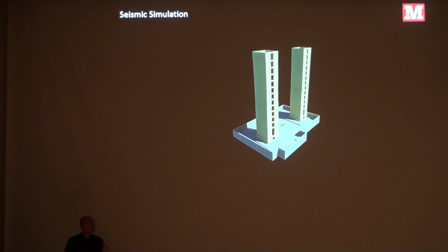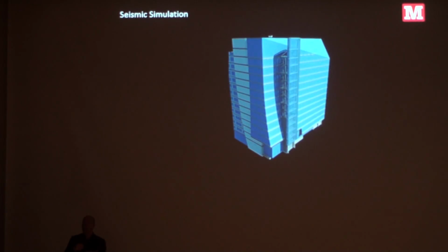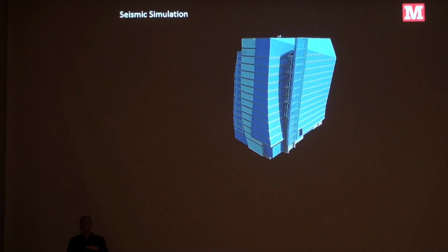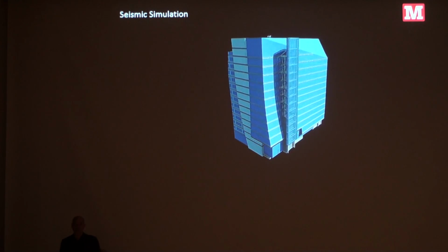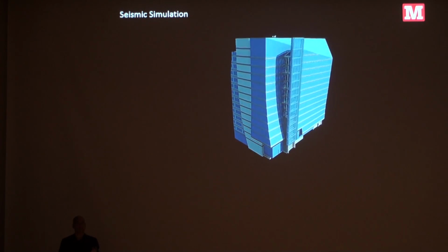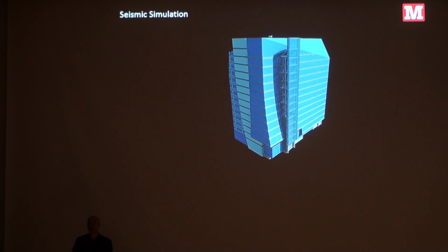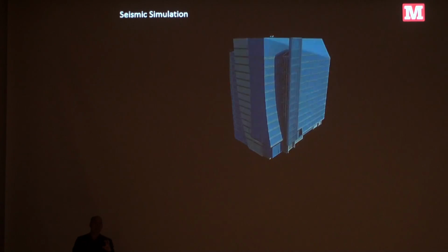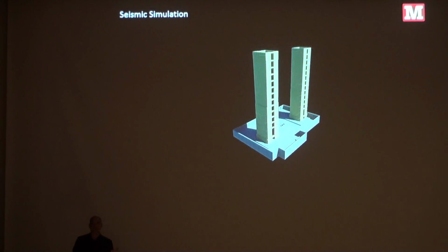The next thing we did is we spent a lot of time getting the floors thinner, because by getting the floors thinner, especially in the steel counterpart, we're able to save 12 inches at every story. By doing that, the amount of skin that we need goes down. But the owner was able, now we're thinking about the business, within the zoning envelope to add another story. And so we didn't make any more money by making the skin cheaper, we made more building by making the structure thinner. In terms of the value engineering, we didn't just cut cost, we added benefit, which was the extra story. We changed the pro forma.